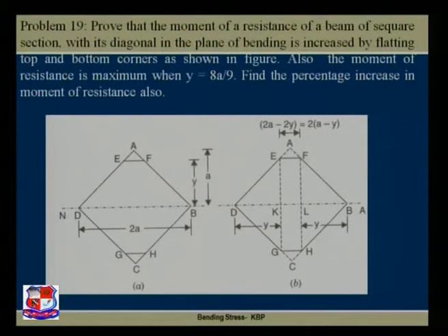The figure is over here, and let us understand the statement made here. The total moment of inertia for this section is the moment of inertia of this triangle plus the second triangle plus the third triangle plus the fourth triangle, and the rectangle, the fifth one, about BD.